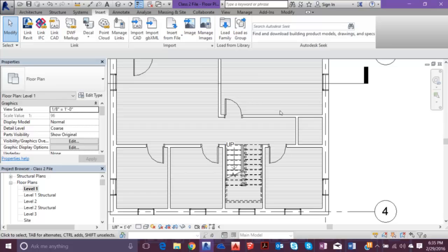If the mechanical equipment is here, we have to make ductwork go from here down here. Revit will not allow us to make this little elbow joint without loading in the duct fittings, so you've got to define where the fittings are, especially if you need to make any T connections, or if you need to go up or down. So you inevitably have to insert each one of the fittings for that ductwork, whether it's pipes, ductwork, whatever.